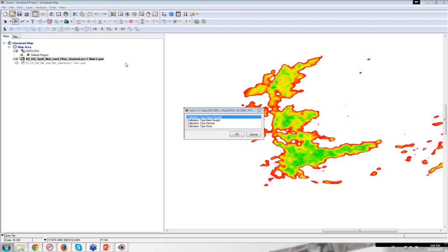Right. So I don't remember exactly which beam modes were used for the Red River. I think they were both standard beam, but maybe from a slightly different viewing geometry or beam position, if you will. So in the case of the Red River, it's not a big deal because it's so flat there that even if you're using a different viewing angle, the artifacts that are present in radar imagery are not as severe. I'm thinking of things like topographic effects, shadow, foreshortening, and layover. So it was easier to handle. Perfect, thank you.